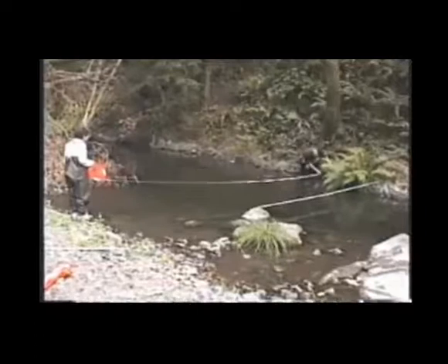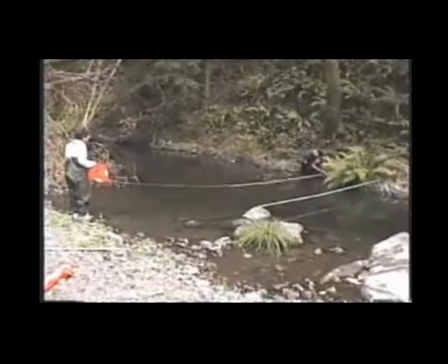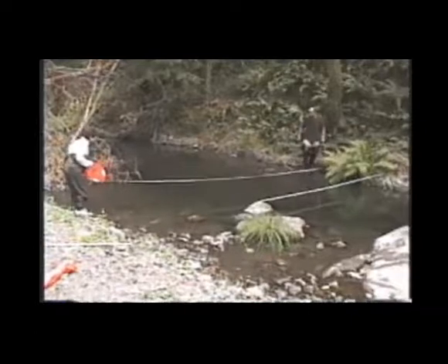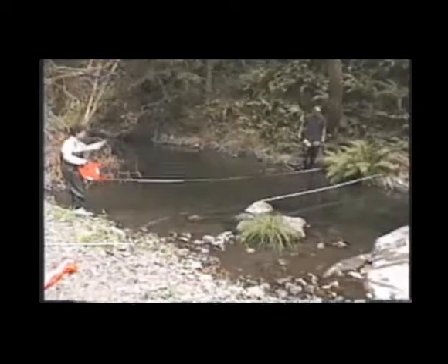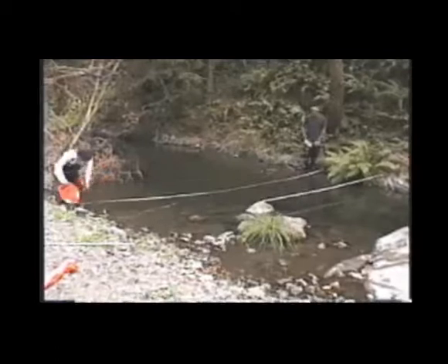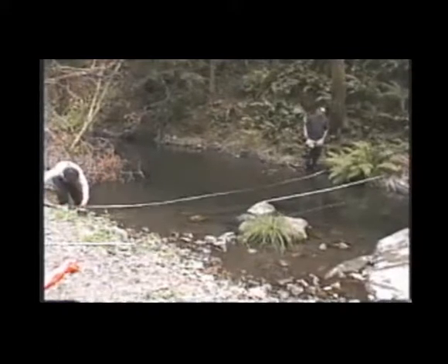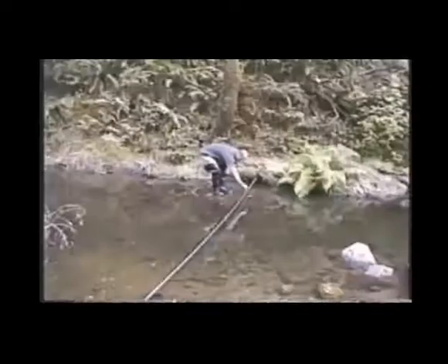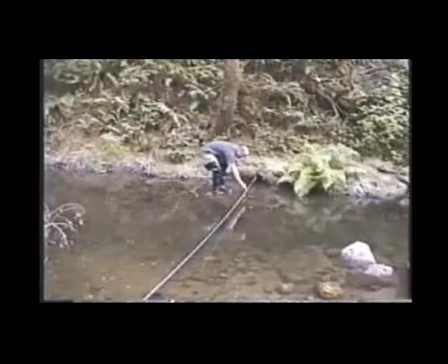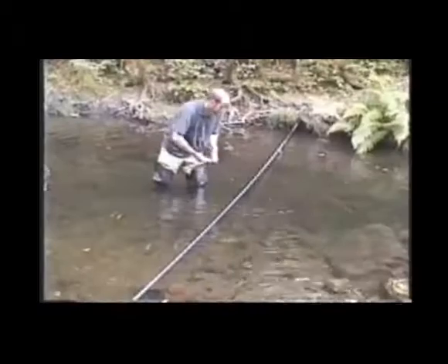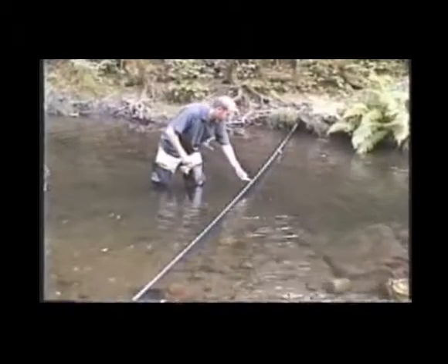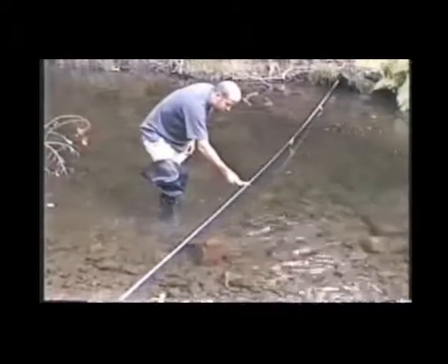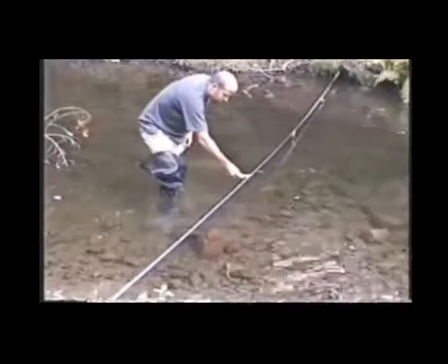And then they measure the width of the stream using a non-stretching tape. You can see the one team member has anchored the tape on the far bank, and then the tape is anchored on the closest bank, stretched tightly. The idea here is to have 5 equal increments across this particular stream. So one of the team members is going to mark out each increment with a clothespin on the tape, and wading across the stream, he is placing a clothespin at each one of the chosen increments.